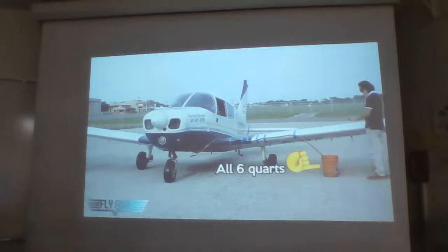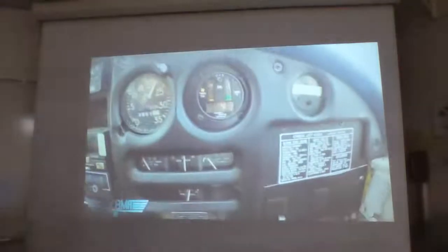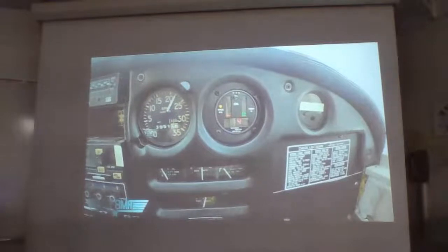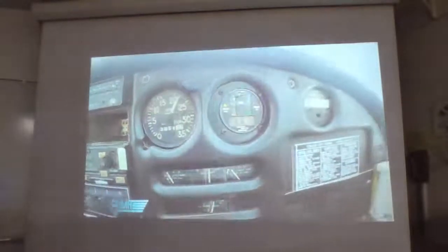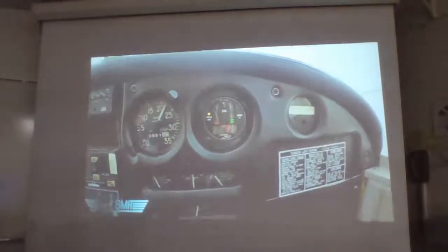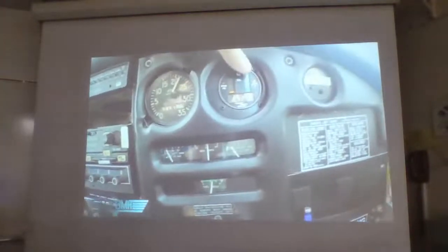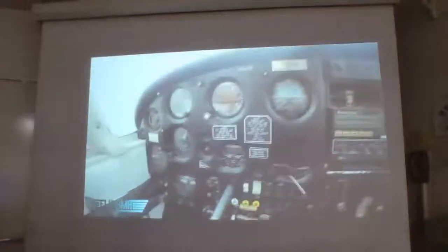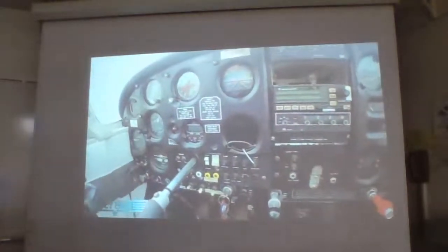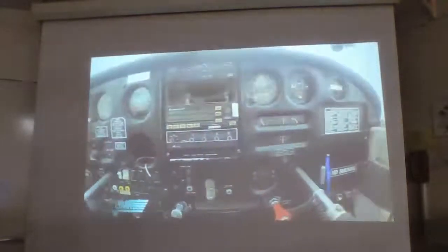Well, not much in the way of oil pressure anymore. Look at good RPM. 4 pounds of pressure. Not really seeing any alarm here, right? We just see low oil pressure, but we don't see any sort of alarm flashing at us. We have no alarm anywhere in the cockpit warning us that, hey, you're out of oil.